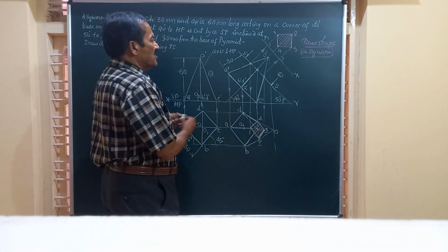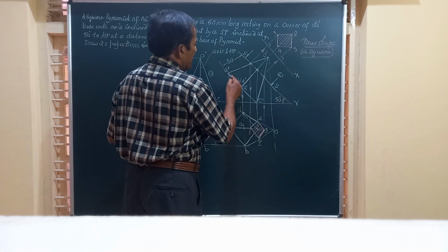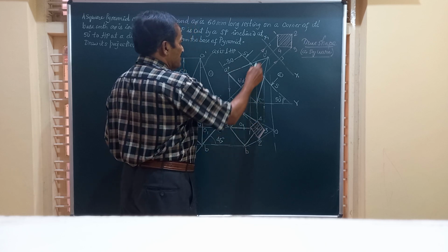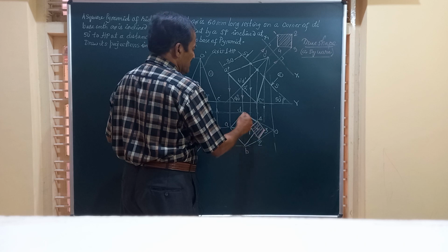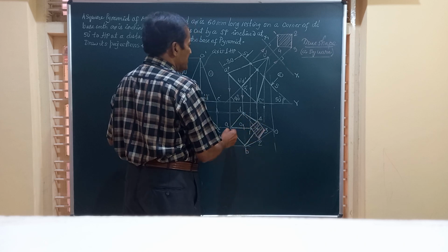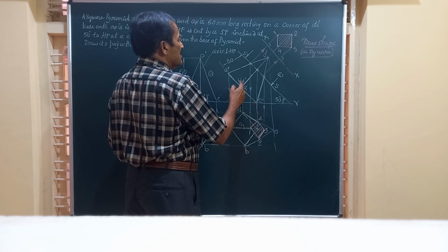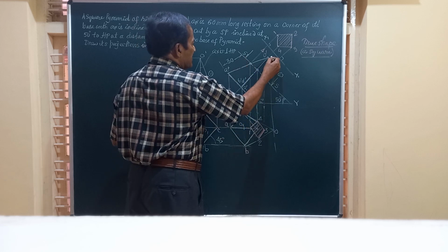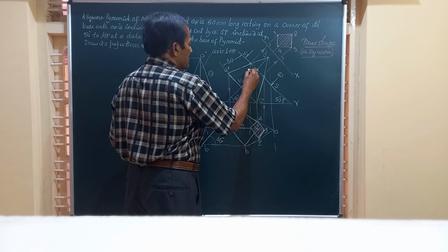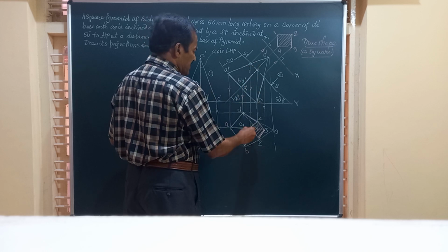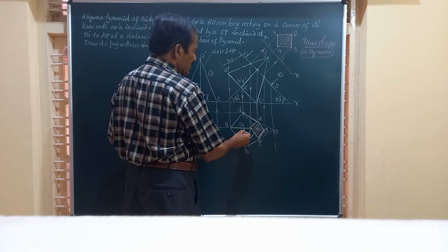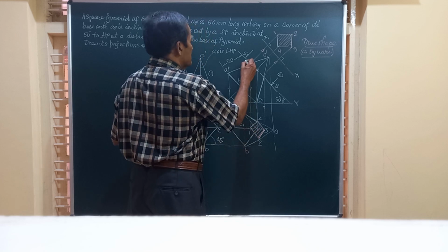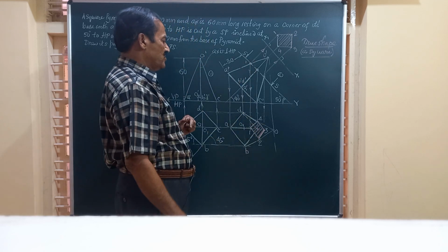Now friends, I have drawn this section plane parallel to the base A dash C dash, and we get all these points before writing the section plane. This is the initial position of the solid, and let us see where the section plane is cutting. Section plane SS is cutting O dash A dash here. I draw a vertical line from there till it touches O A, and we obtain this point. This is our point 1, say on OA we have got 1.